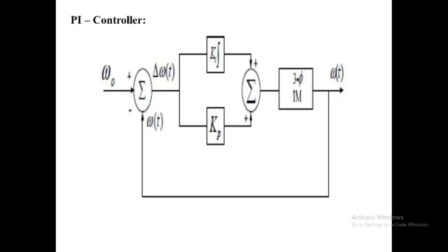In the industry, PID controllers are the most common control methodology used in real applications. The PID controller has all the necessary dynamics: fast reaction on change of the controller input, increase in controller signal to lead the error towards zero, and suitable action inside the control error area to eliminate the oscillation. Derivative mode improves the stability of the system and enables an increase in the gain K and a decrease in the integral time constant Ti.